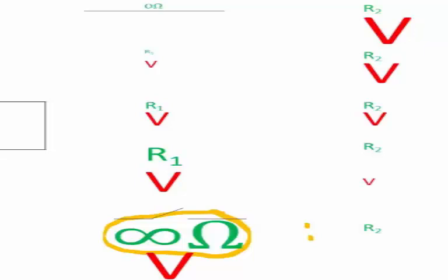Resistor 1 is so greedy that in comparison, it's as if resistor 2 is a good conductor. And so the open switch of infinite resistance would take all the voltage. If the battery supplies 9 volt, 9 volts will be across that open switch.